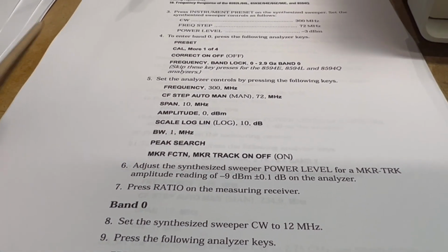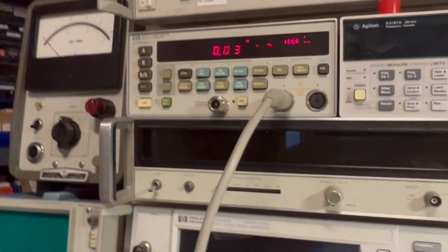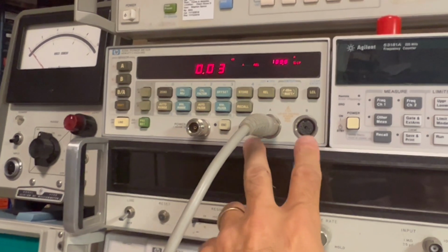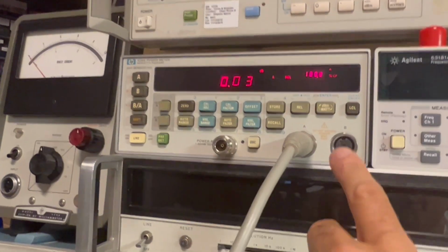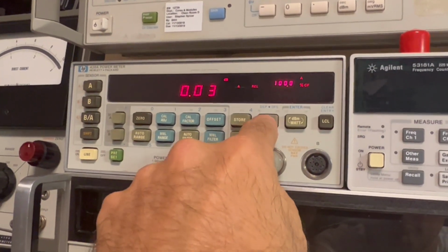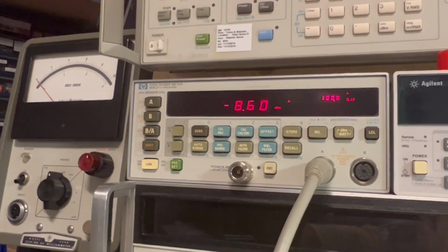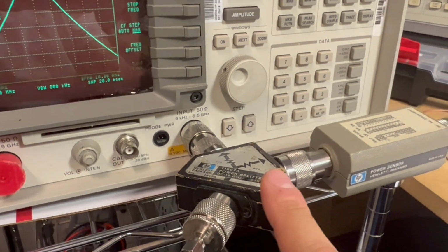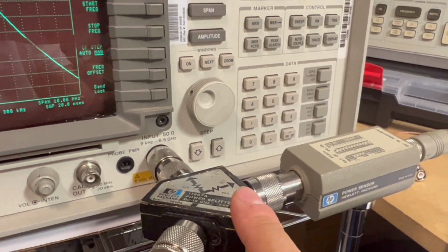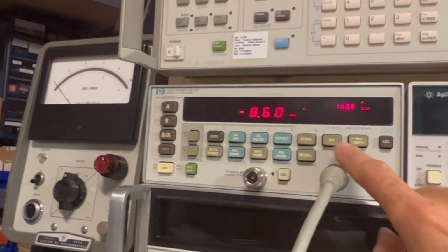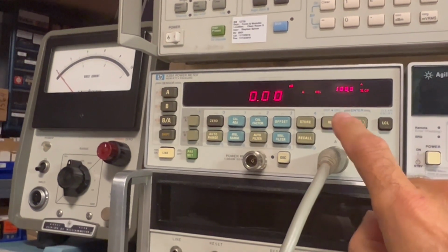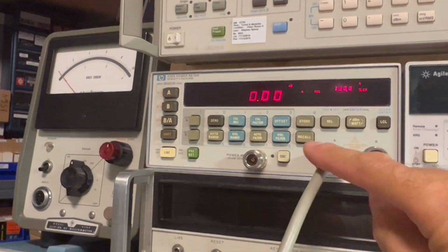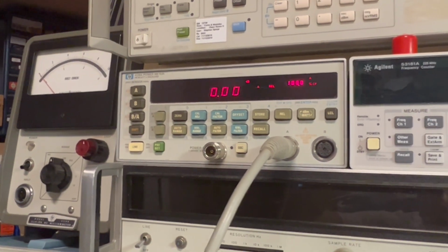Now, on my power meter, if I want to do a ratio, I have to use two power sensors because it's a dual port meter. But what we can do is we can take a relative reading, and that's what I've got here. So we go out of relative mode, we see that that is our current power reading off of our power splitter here. So we're at our 300 megahertz reference signal level, and we're seeing a power level there. Now when I hit the relative button, that'll go to 0, and so now all of the readings that we take will be relative to that initial power reading at 300 megahertz.